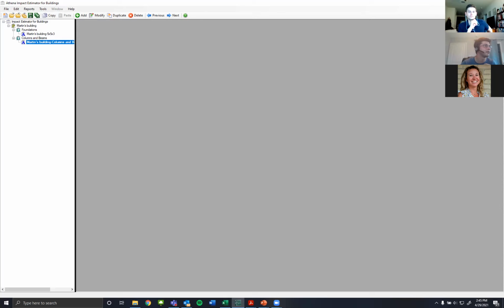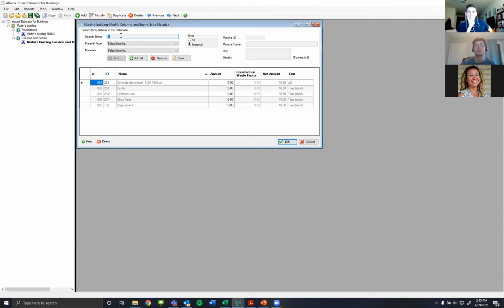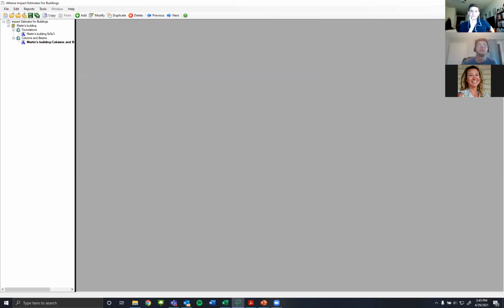But once I have, so we create a project, we defined building information, we added operational energy, we added a material. Oh, and you can also, to go back here, you can search. So if I know I have a 1/2 inch, I know that gypsum looks like that. So I could just put the 1/2 and it shows me everything that's 1/2. That's another way you can search for materials. And so that's adding materials.